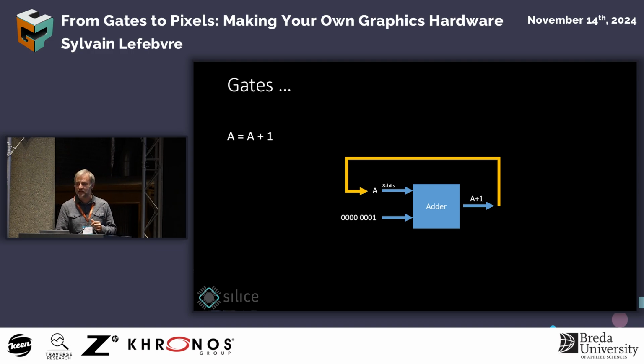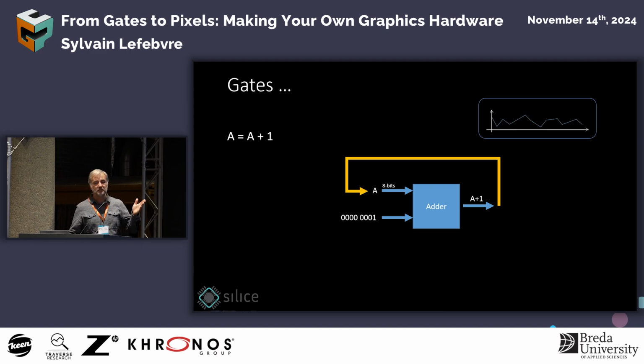And the problem here is that the circuit will be free running, and as soon as the output is updated, the input is changing, the circuit tries to update the output as quickly as possible, and this goes on and on. And the problem that is even worse here is that you have several wires that go through different paths in the combinational circuit, so they don't have the same delays. So things will completely go out of sync, and what you get out of the circuit is actually mostly random. Right? So what I've just built is called a combinational loop, and this is a bad thing, right? Normally, apart from very specific rare cases, you never want to build such a combinational loop. So you need something else, and what you need is synchronization to make this work.